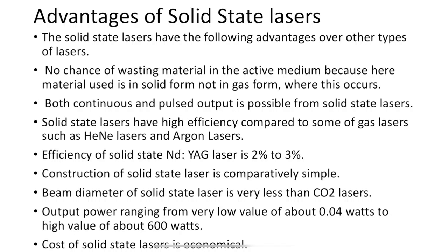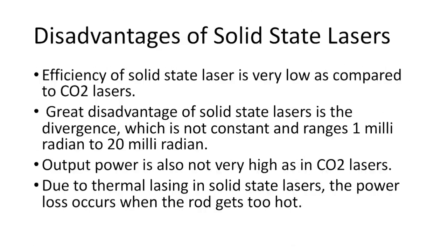Construction of a solid state laser is comparatively simple. Beam diameter of the solid state laser is very small compared to CO2 lasers. Output power ranges from a very low value of about 0.04 watts to a high value of about 600 watts. The cost of solid state lasers is economical.